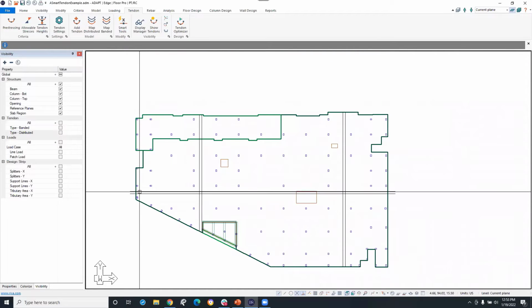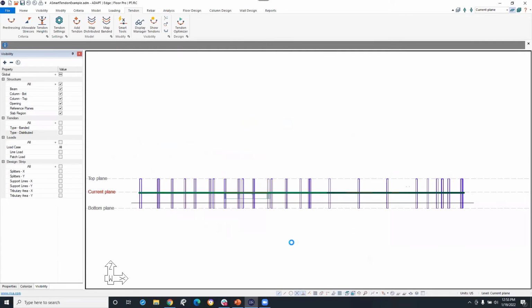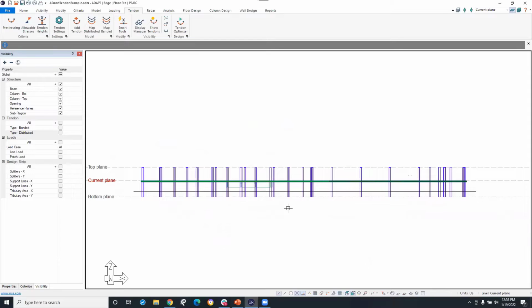Now, you'll notice some other potential differences. This column, we now have a bottom and top option. So let's go to the side. I'm sure if you're like me, there were plenty of times when I did a punching shear check, or I had a planted column that kept pestering me, thinking, my brain keeps telling me it's supporting the slab, but it actually isn't.